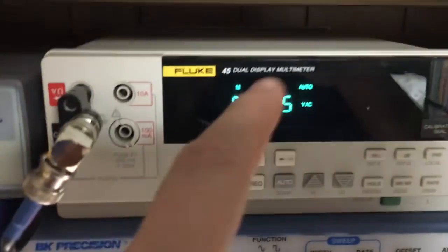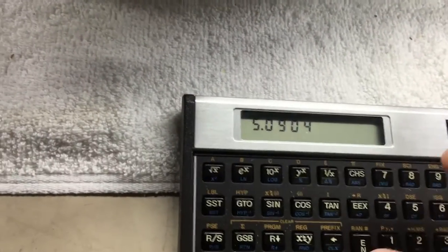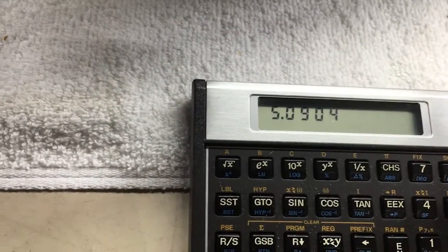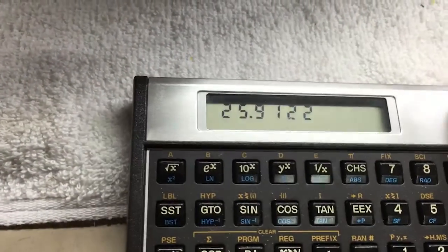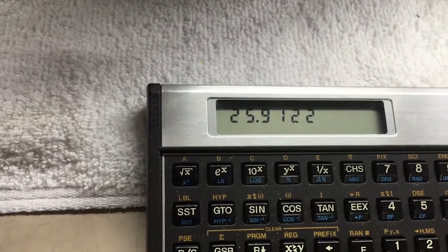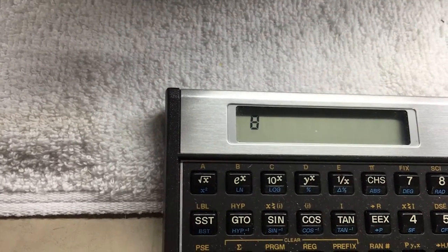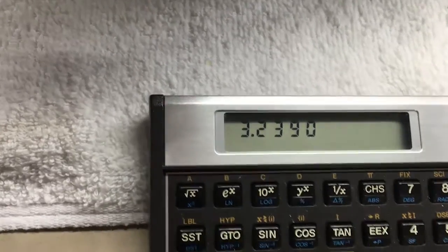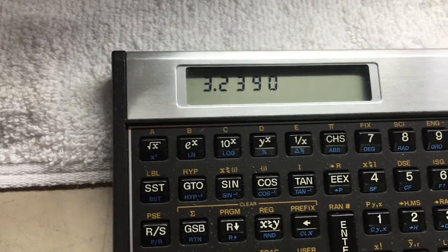So, you know, it's easy for me. I can just kind of glance up here and see this number. And then if you'll remember the math I told you, right? So once you know the RMS voltage, you can, in this case, take that number and we can store it, and then we can square it. So we're going to do that, and we get 25.9122, and we're going to then divide it by, and if you remember, you could do V squared over R. R is 8 ohms here, so we divide that out, and we end up with 3.23 watts of power that this thing is putting out right now at this 7.25 volts peak.